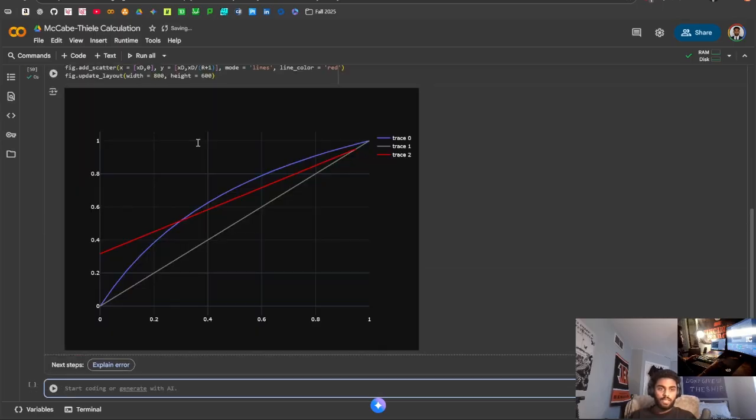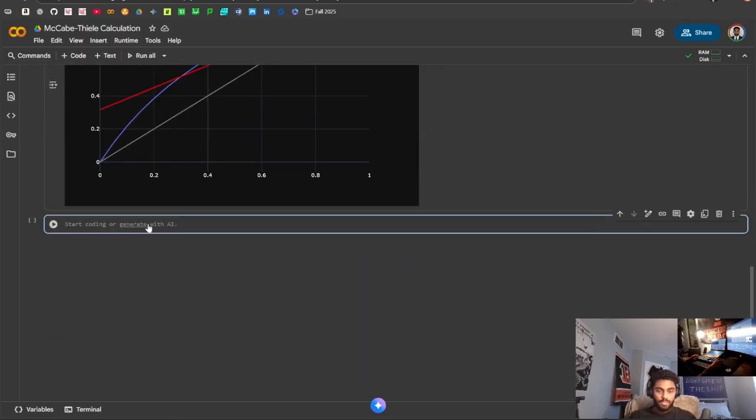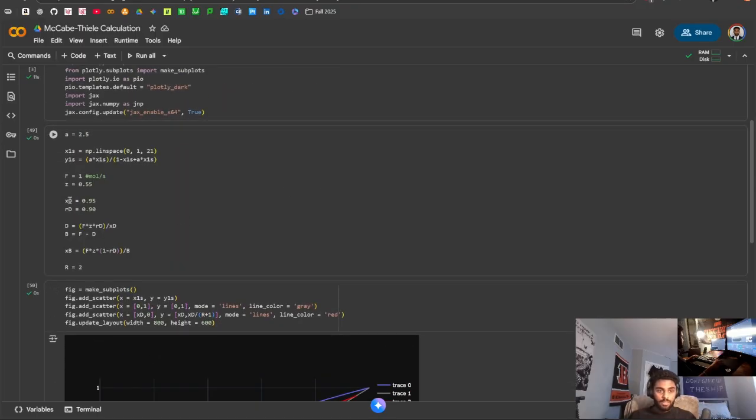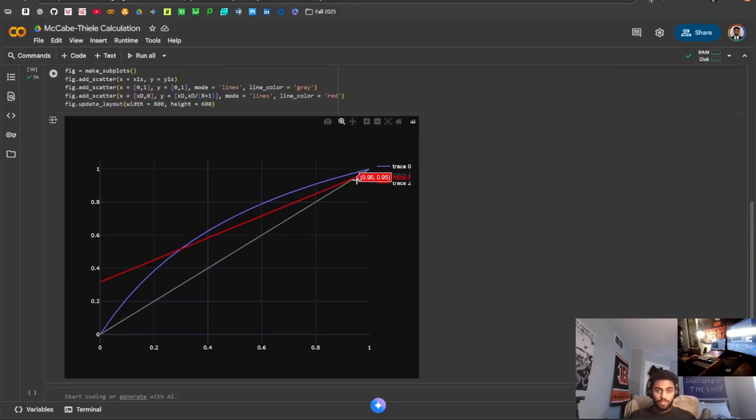Oh, it's because I moved this stuff up here. But anyways, here we go. Remember, we set our distillate x to be 0.95. So that's exactly where that's starting. And our y is equal to our x distillate. So that looks great, and we're going all the way across to where x equals 0. So I'd say that this is a pretty good rectifying line.